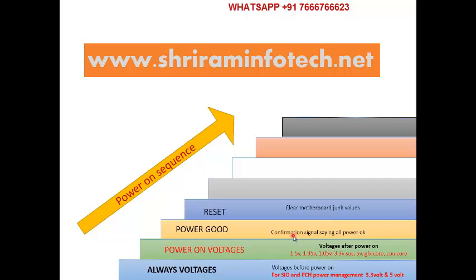After that, the next signal is called reset. What does the reset do? The reset cleans the entire motherboard. If there is any junk information or junk value, whether in the RAM, the processor, the PCH or wherever it may be, it is cleared by the reset signal. So this signal is very important.